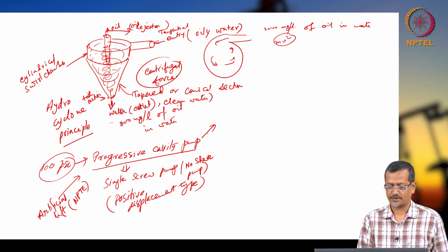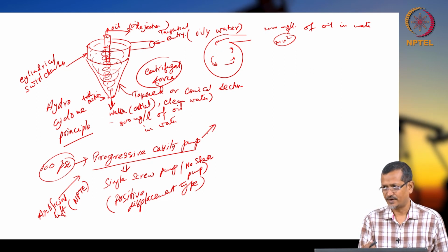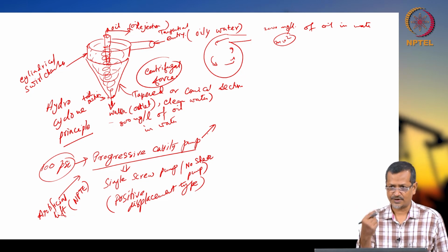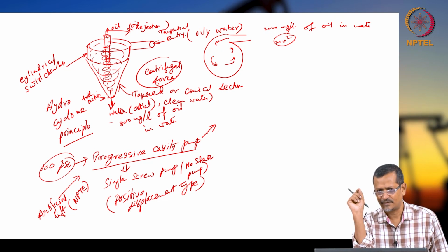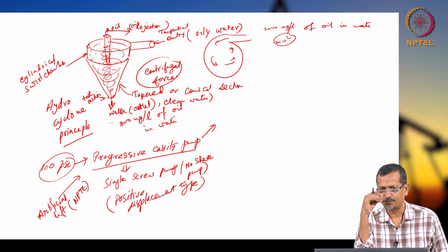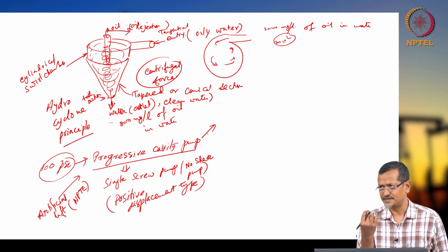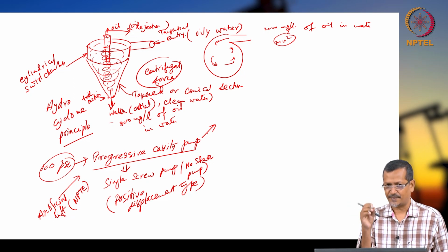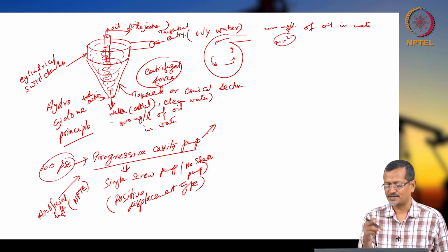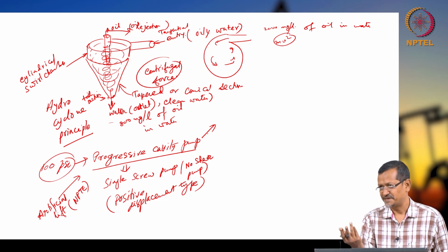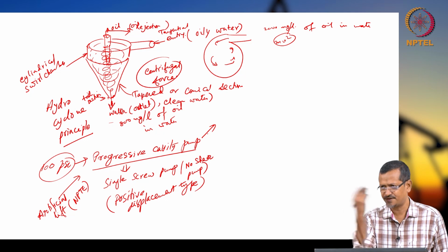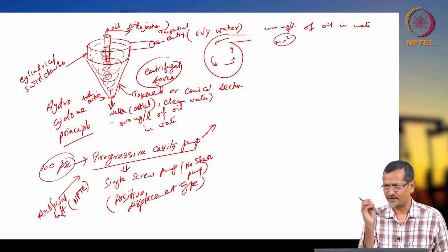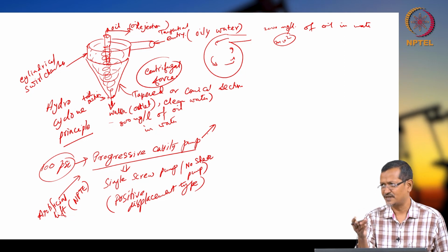What is this issue of shearing? Shearing is like a centrifugal pump, which rotates at very high velocity. When it rotates at high velocity, say I have a 500 micron size oil particle, because of the high velocity and huge turbulence inside the pump, the particle will be broken. When the particle is broken, it creates very small particles. So separation from any device will be difficult, because your main purpose is to increase particle size. A very high velocity pump like a centrifugal pump gives shearing action because of high turbulence, so the particle will be broken into very tiny particles, and again separation will be difficult.